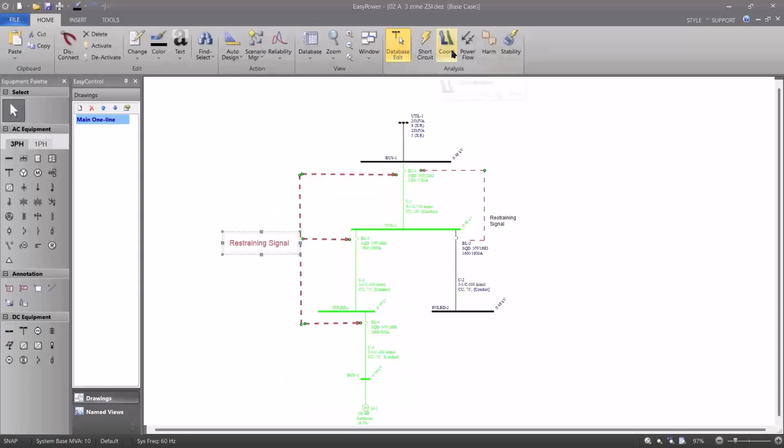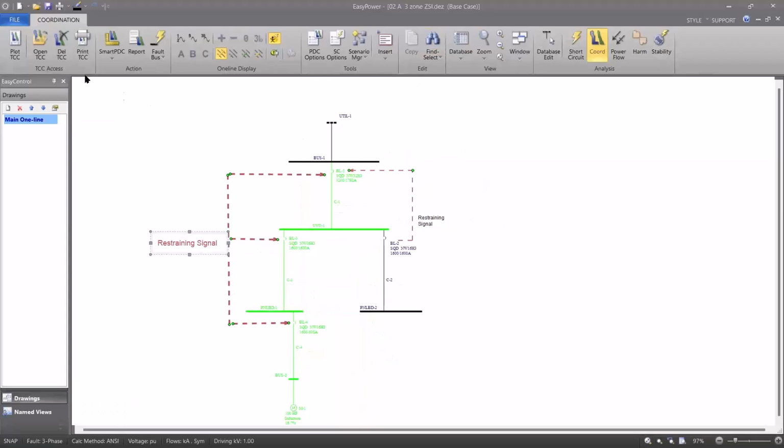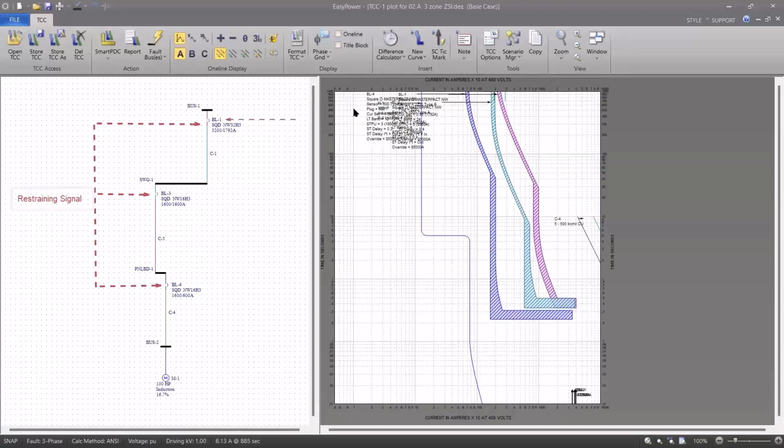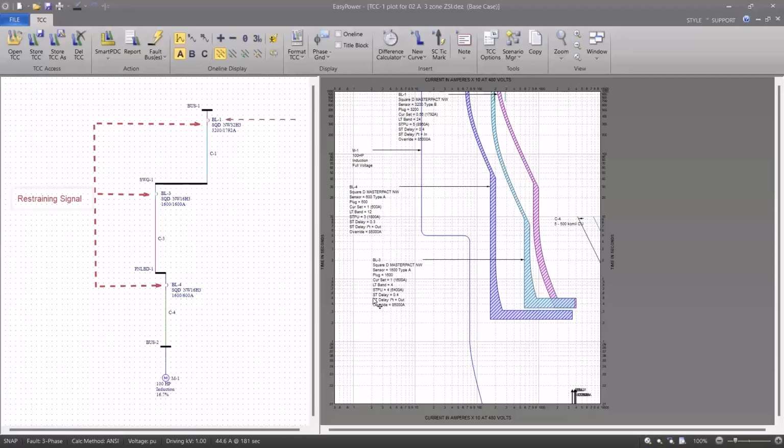display on how this works. So I'm going to look at these three breakers, BL1, BL3, and BL4. Normal operations, if we kind of reduce this. Oh, the other thing is maintenance mode, if left intact, will contradict selective coordination, whereas zone selective interlocking, because the manufacturer will be involved in setting the profile for the upstream breakers, can maintain coordination.